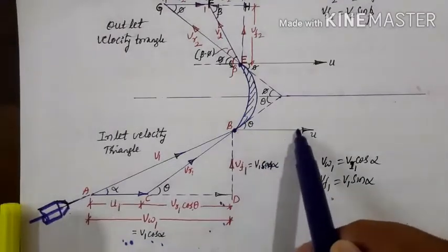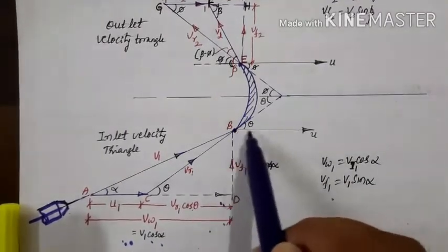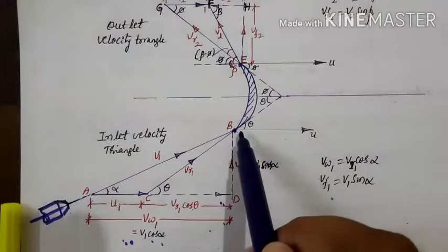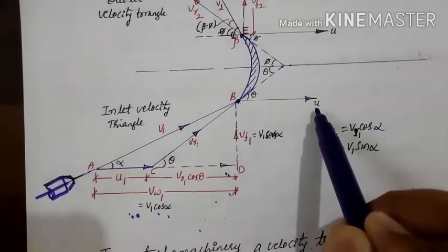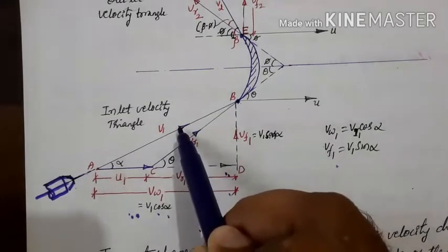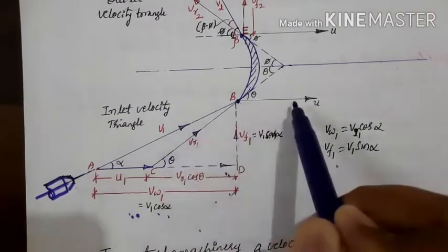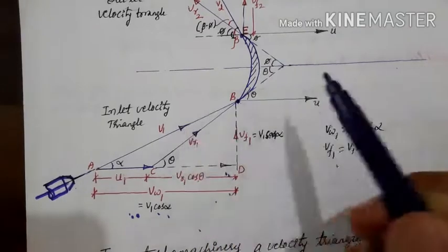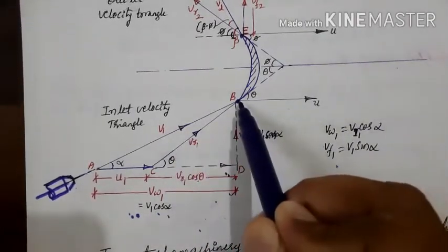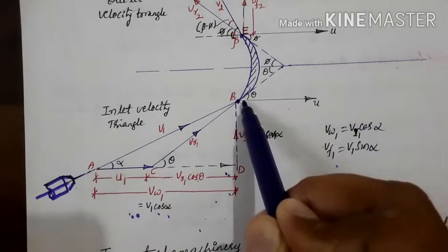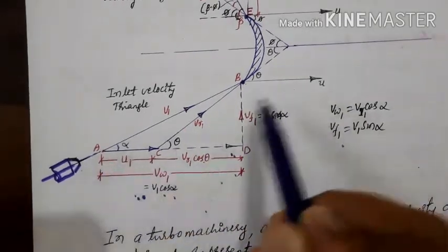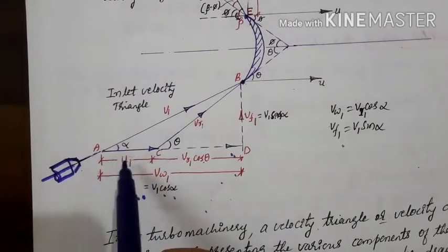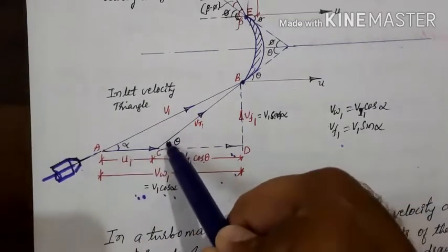And this vane is moving as I explained earlier, and this velocity is taken as u here. The jet as well as the vane both have direction as well as magnitude. Let us shift this vector and keep it here with the same magnitude and direction, that is u1. Then the difference of these two will be VR1.